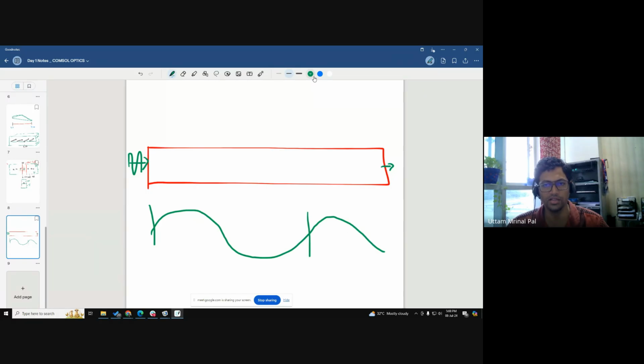So basically, the mesh requirement is it requires at least second order mesh elements. Now, second order is what we discussed in the first session. So it's a linear elements. It requires at least five second order mesh elements per wavelength. So it could be something like this. Okay, sorry.